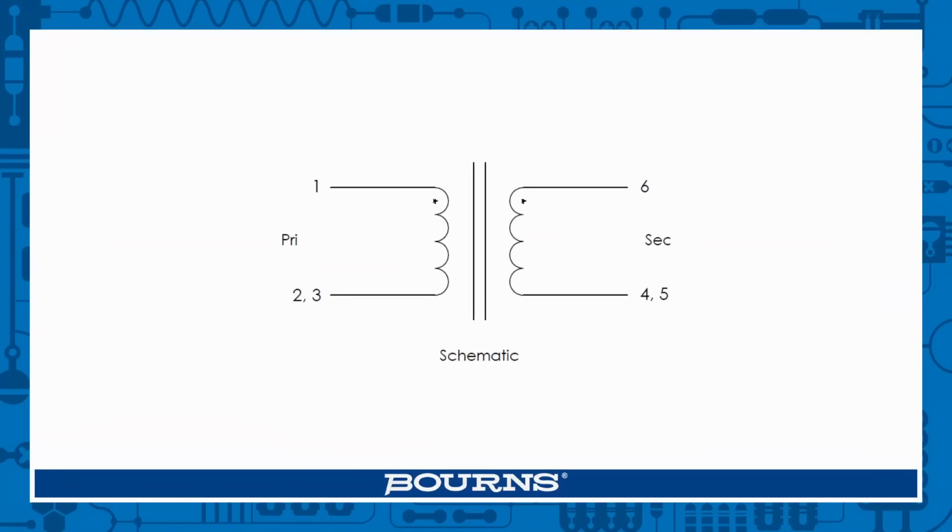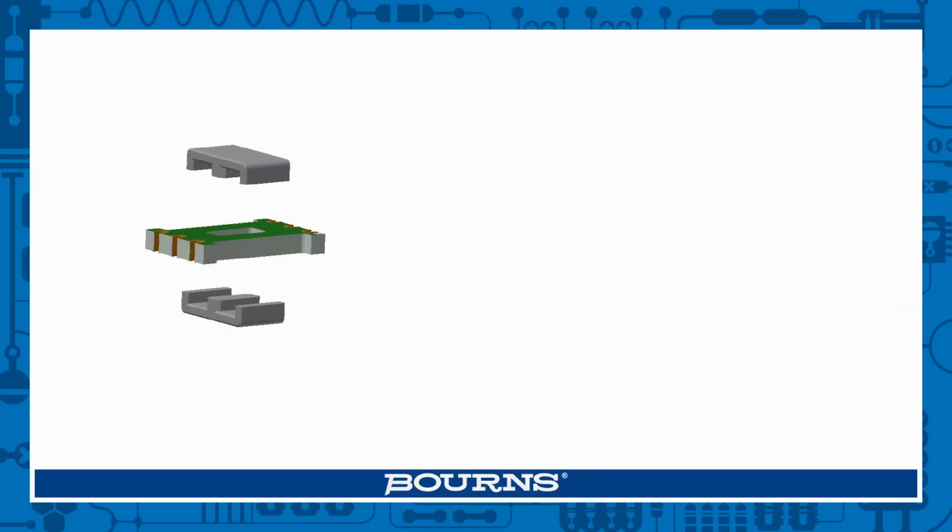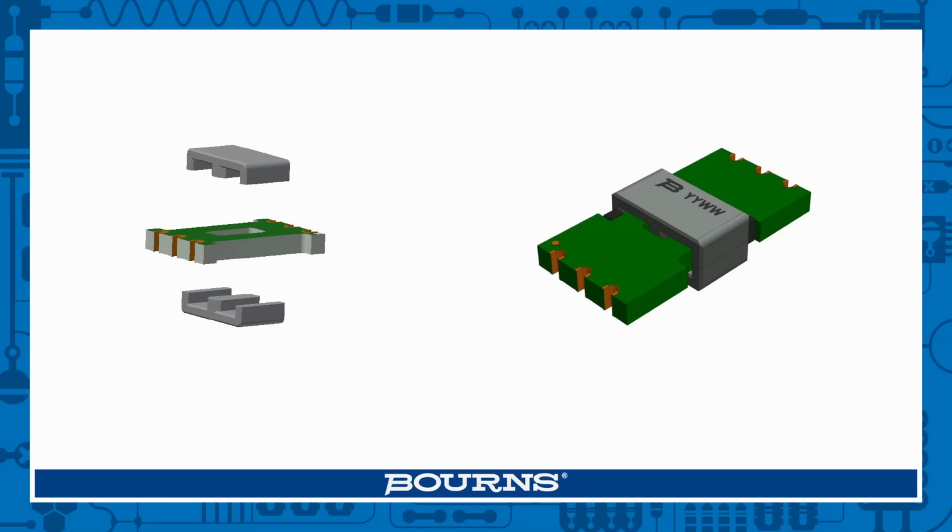And if it's a transformer, you would have a primary side with one spiral, and then a secondary side, another spiral directly located underneath that. The separation between them can be controlled to a very fine level. The assembly of the transformer would be quite straightforward. Once you, let's say, print the windings, the coils, on the planar substrate, the assembly is quite quick.